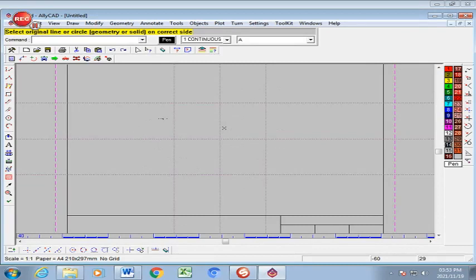Now, just to give you an image, I'm going to go to my continuous line, this one here, which is the second one, and I'm going to click on that one, run right across. My cursor is now almost like a bird with a cross, but I don't want that one. I'm going to go to this second one over here, which is my box, and this box allows you to jump. So you can click anywhere with that point encompassed in the box, with the corner anywhere in the box.